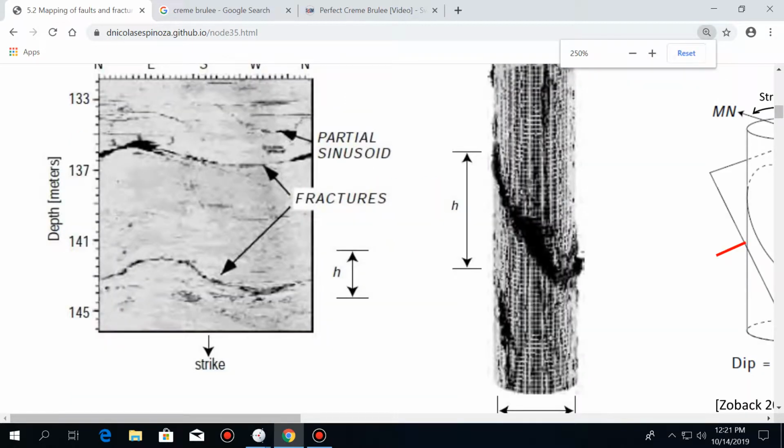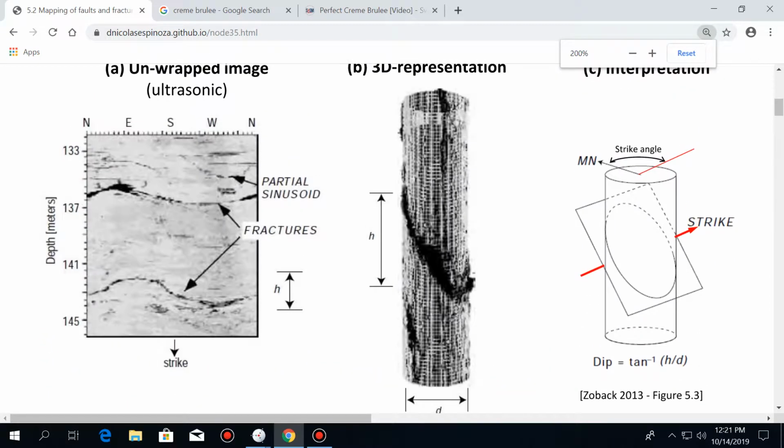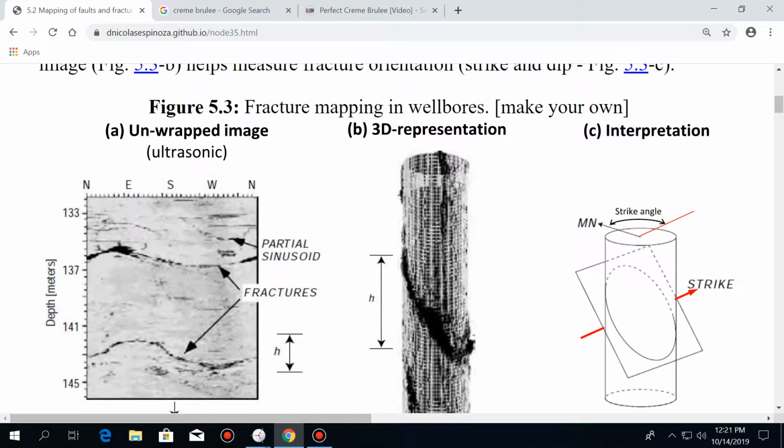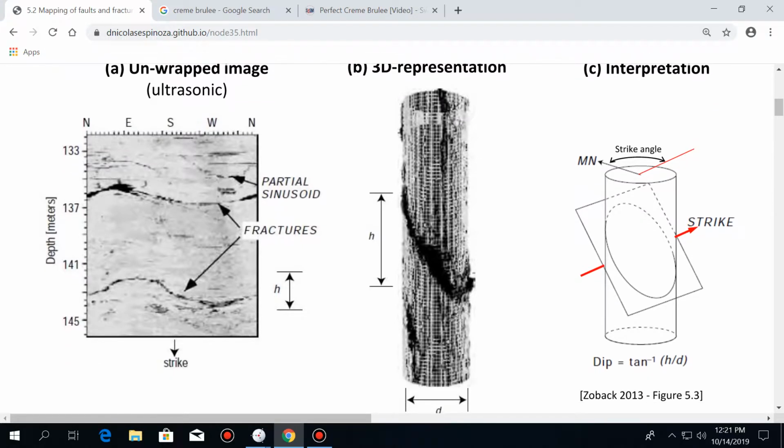Well, in wellbores with this formation microimaging, either if you do it with electric resistivity, like those that you see over here, or this one, which is with ultrasonic wave velocity, you can measure either resistivity or travel time, and whenever you have fractures, there's going to be an anomaly in that measurement that's going to signal that fracture very well.